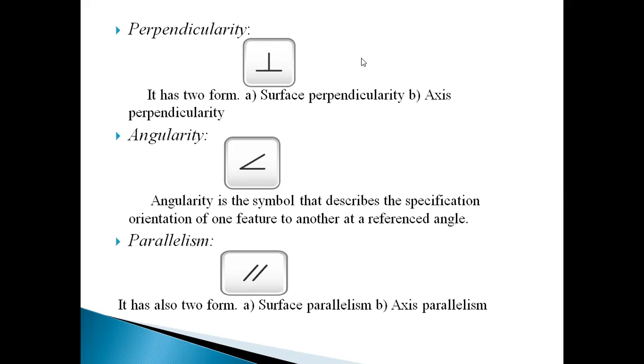It is generally a 2-dimensional line referenced to another 2D element, but more commonly it relates to the orientation of one surface plane relative to another datum plane in a 3-dimensional zone. This tolerance indirectly controls the angle by controlling where the surface can lie based on the datum.